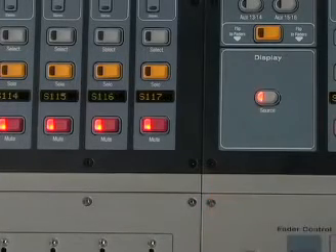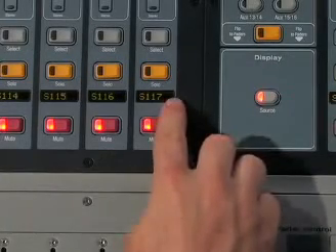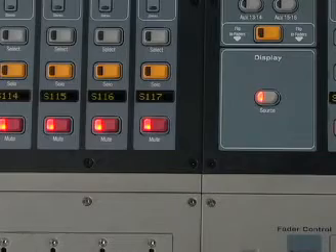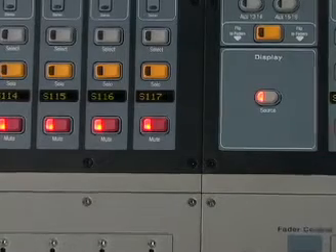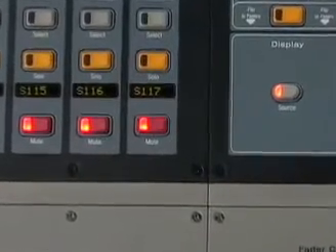A handy Patchbay feature on the D-Show control surface is the source button. This can give you a quick indication of the origin of a signal. If you press this button, the 6-character display switches modes and now tells you the stage or front of house source connection for the given channel. This display indicates stage rack 1, channel 17.